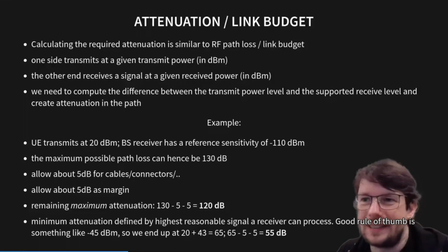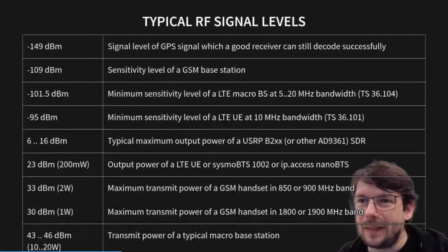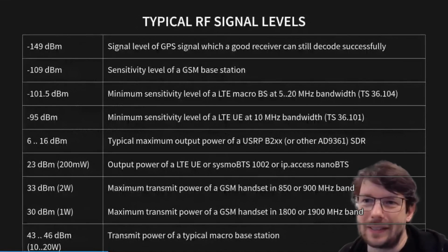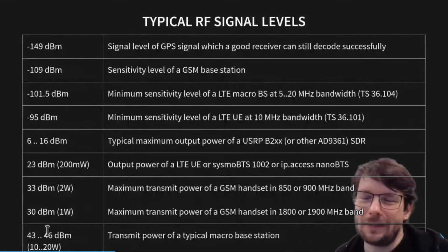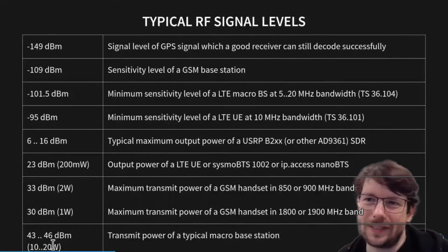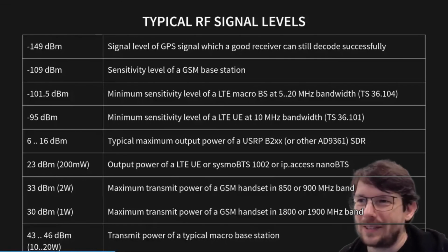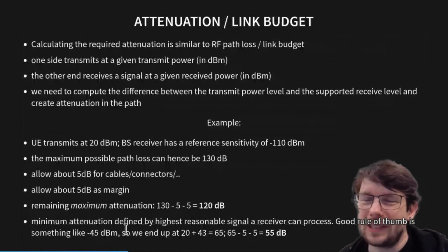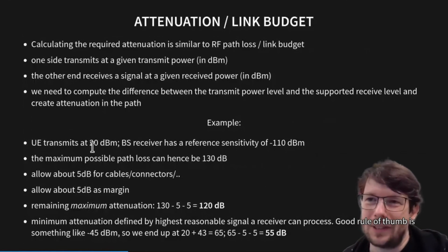then, if we look back at that slide, 40 watts would be 49 dBm. As the slide says, 46 is 20 watts, 3 dB more is twice the amount, so it would be 49 dBm. So in that case, the downlink signal level at the transmitter would be 49 versus 20, 29 dB higher than in the uplink direction, meaning we need additional attenuation in the downlink direction to compensate for that, to make sure that we fulfill the requirement in both ways.